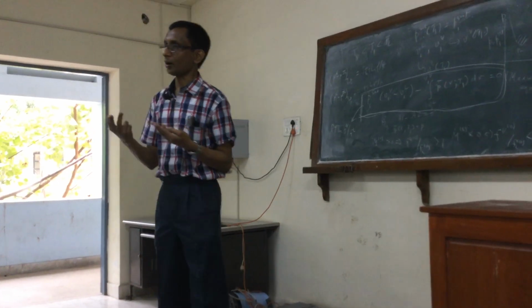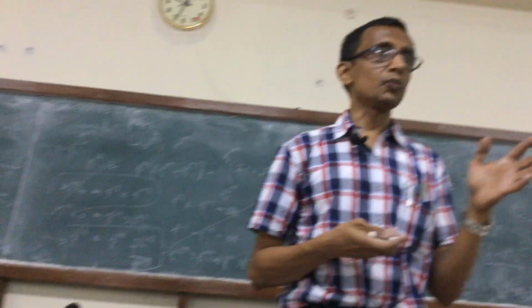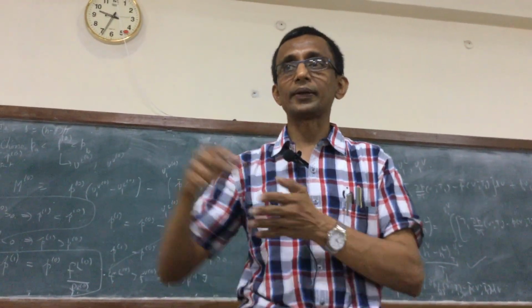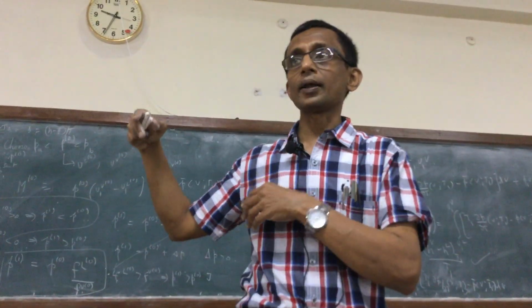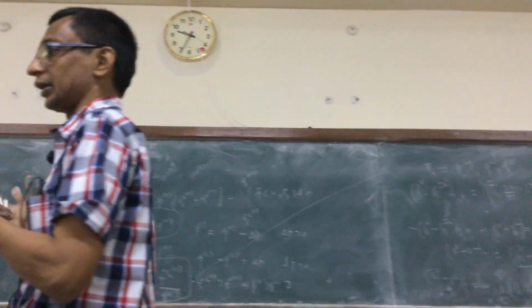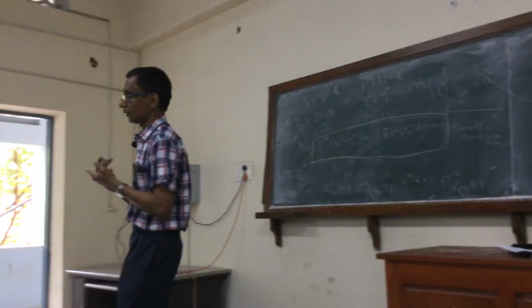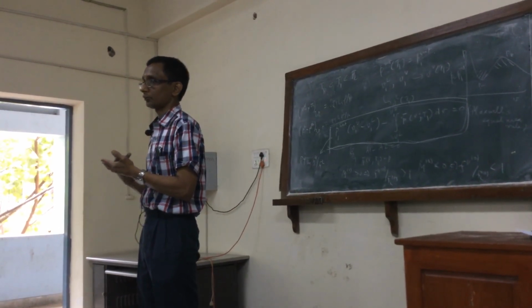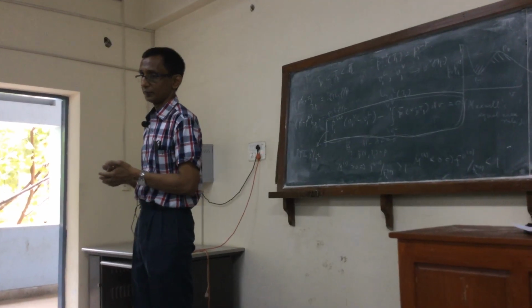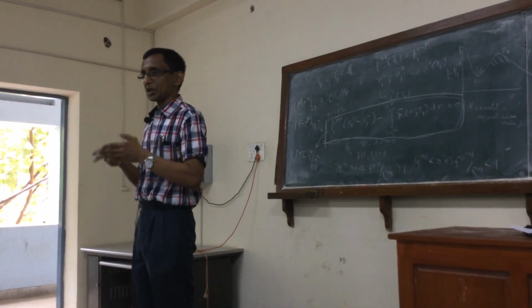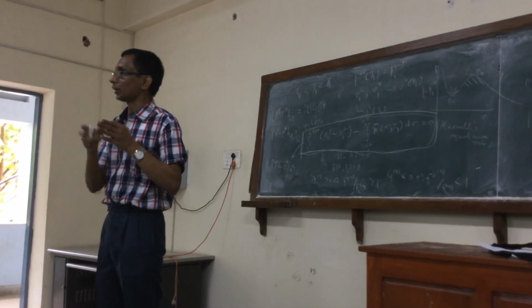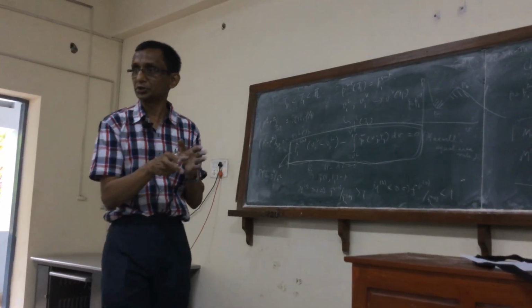Right? So if you saw earlier changes of state, you get two terms, one which contains the derivative of the property with respect to pressure or volume, that is related to the equation of state. Another that will contain the specific heat. So you need basically two inputs to calculate any change of state, property change of state, right, within a single phase. But if there is only a change in pressure or volume and no change in temperature, then the equation of state alone will give you that change.